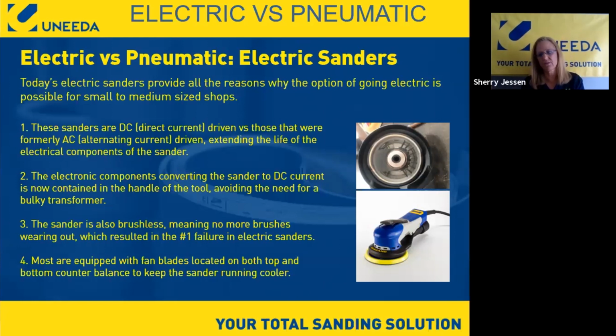The drawback is that if you hammer down on this handle, on the sander, for a long period of time, it can overheat. The good news is if it overheats, it's a simple fix. It's a series of buttons. You unplug it, press a series of buttons, reprogram it, plug it back in, press 2 more buttons, and you're going again. But that has been one of the drawbacks of putting it in the handle, because it does allow the heat right there at the motor. But outside of that, they work fine.